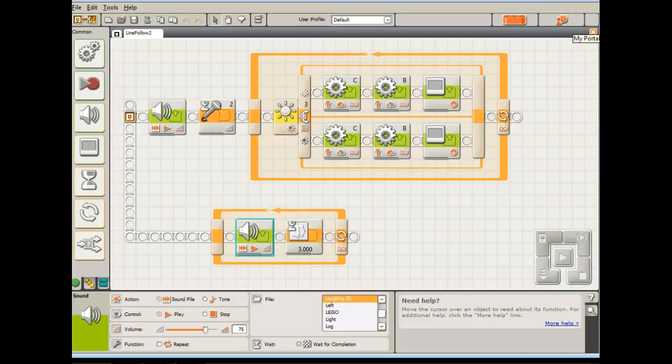None of these robots use a stop in the program. We have a button on our teach pendant called hold or stop or something like that that we hit, and that is controller based. You understand? Normally you don't want a robot to be programmed to stop. You can pause it and make it sit still, but it's always waiting on something to happen.